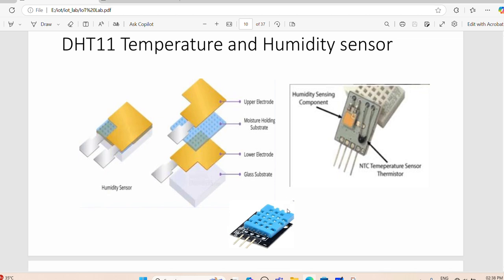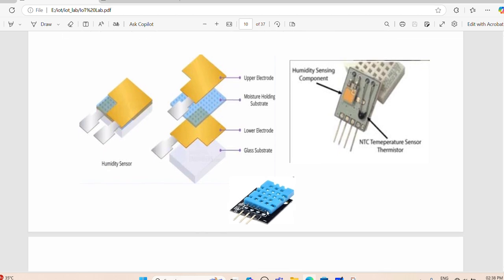So the DHT11 sensor which we are using, you call this a DHT module, 11 module, has got 3 pins. As we know, this sensor acts as an input device which collects the humidity and temperature happenings in the surrounding. So this one pin, input pin, will be acting as an input port. If I want to interface it with a microcontroller, then we've got VCC and ground.